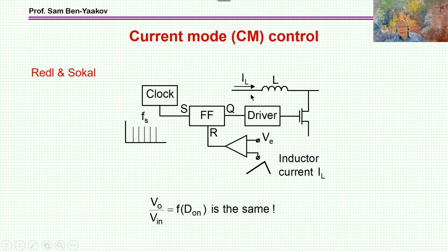Now, since the transistor is turned on, the current starts to build up. Because, say, for example, this is like a boost converter, so there'll be V in here, at the point of the transistor. So we have the voltage imposed on the inductor, and the current goes up.